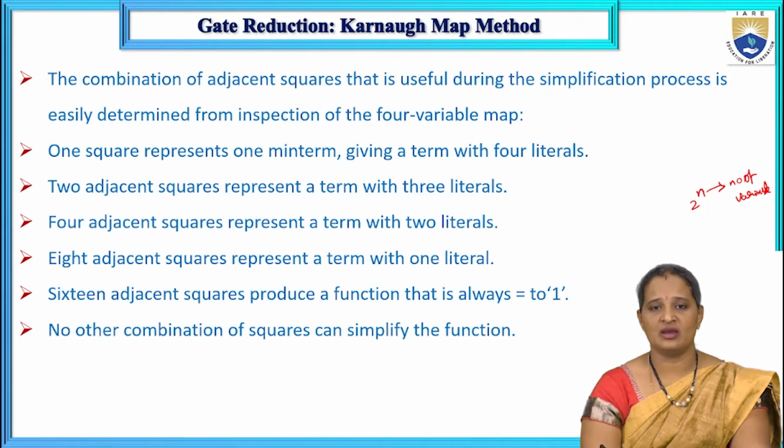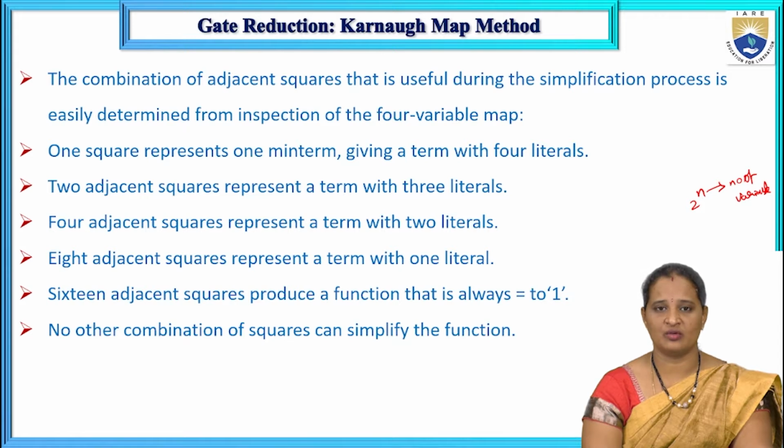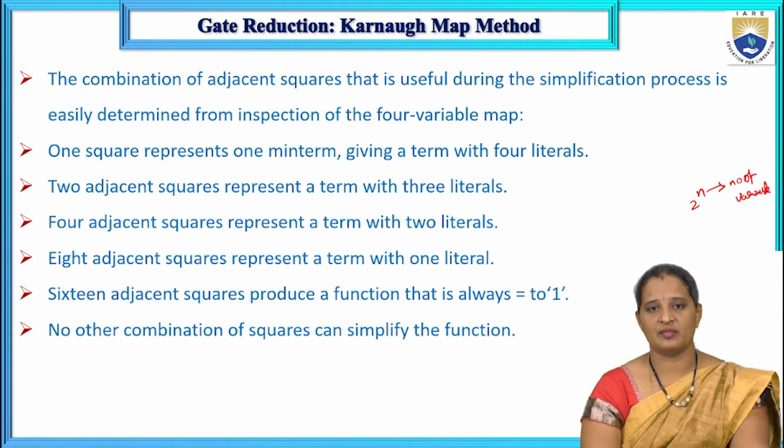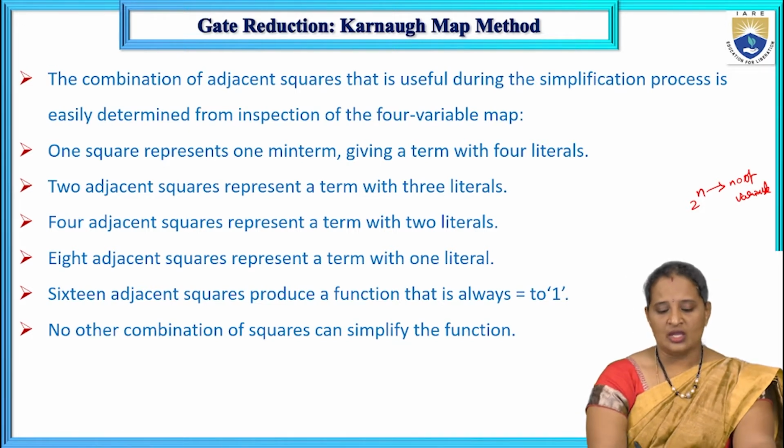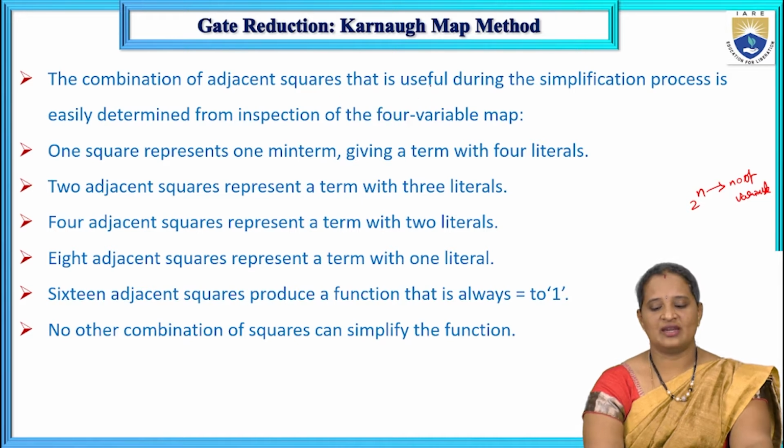This is to make two neighboring cells adjacent. If we use binary code, even though they are neighboring, they cannot become adjacent and we cannot group them together. So that is why we follow the order of binary representation in gray code order.